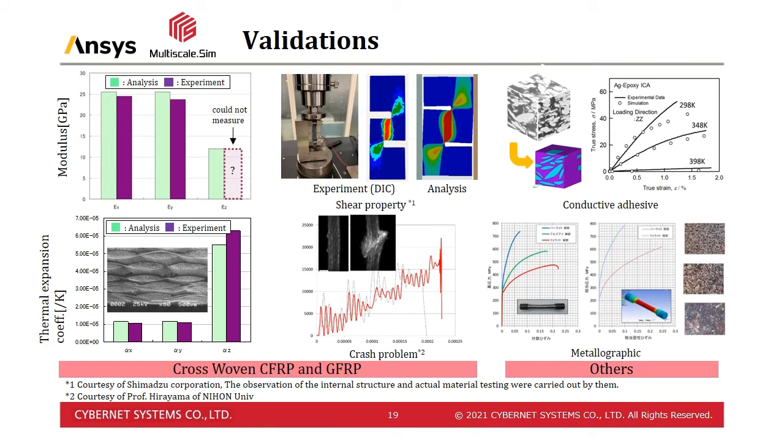When compressive load is applied from the in-plane direction, a region where pure shearing mode dominates can be observed between the notches. We confirmed that the strain distribution quantitatively agrees with the real test by preparing accurate anisotropic properties.